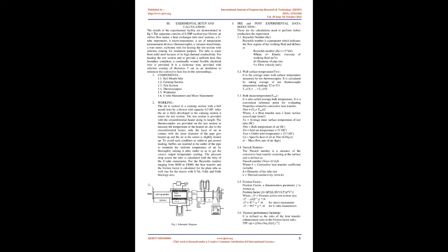3. Compound techniques. 3.1 Rough tube wall with twisted tape. 3.2 Rough cylinder with acoustic vibrations. 3.3 Internally finned tube with twisted tape insert. 3.4 Finned tube with fluidized beds. A compound method is a hybrid method in which both active and passive methods are used in combination. Two or more techniques may be utilized simultaneously to produce an enhancement.